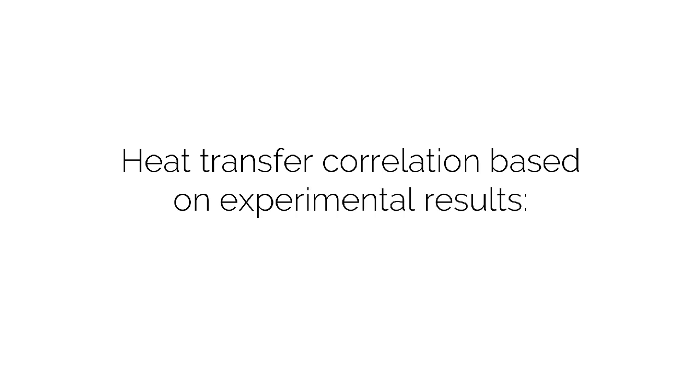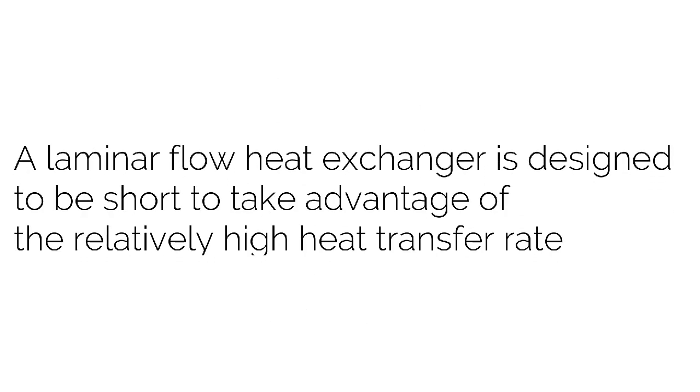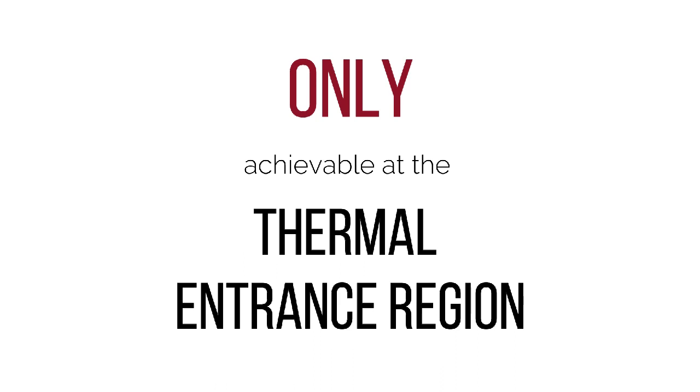Heat transfer correlations based on experimental results are typically divided into those applicable in the thermal entrance region and those that apply in the fully developed region. In the case of laminar flow, it is important that we are aware of this distinction, and normally a laminar flow heat exchanger is designed to be short to take advantage of relatively high heat transfer rates that are only achievable in the thermal entrance region.